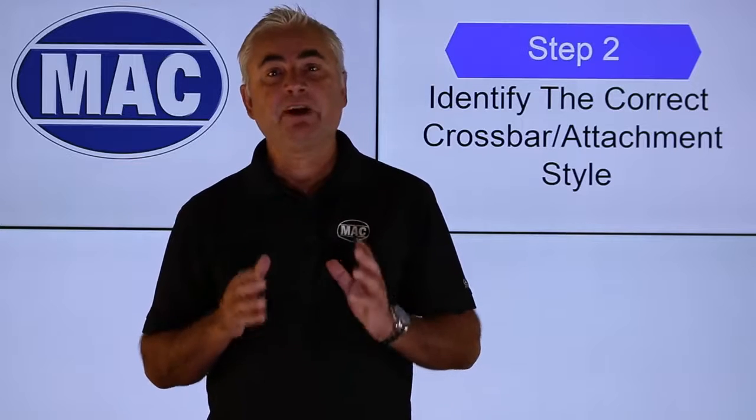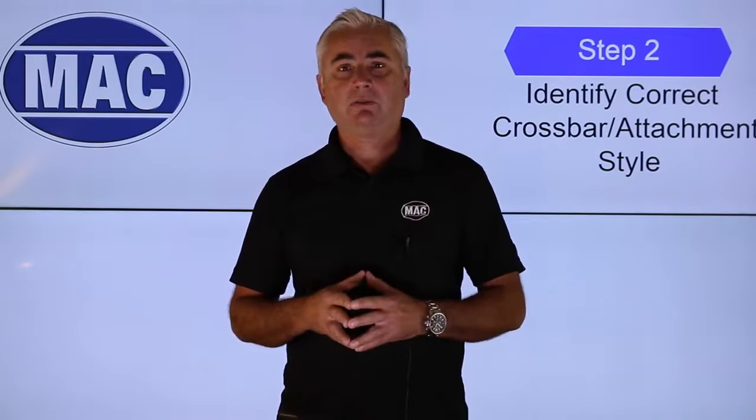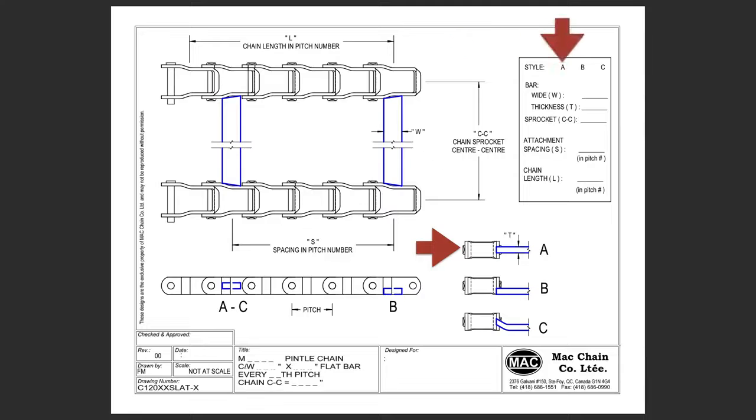Step number 2, identify your crossbar style. There are 3 different styles of crossbars used, depending on your application. Style A, the crossbar is located in the center of the sidebar. This allows weld on top and below the sidebar. Style B, which is located flush with the bottom of the conveyor and flush with the bottom of the chain. Style C, which is the most common, is also located flush with the bottom of the conveyor, but is formed on the ends, which allows you to get weld on top and below the crossbar.